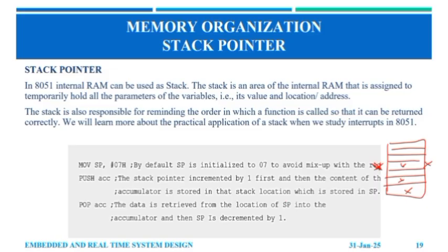It means the stack pointer is incremented by one first, and then the content of the accumulator is stored in that stack location, which is held in the stack pointer register. For pop, the data is retrieved from the location of the stack pointer into the accumulator, and then the stack pointer is decremented by one.